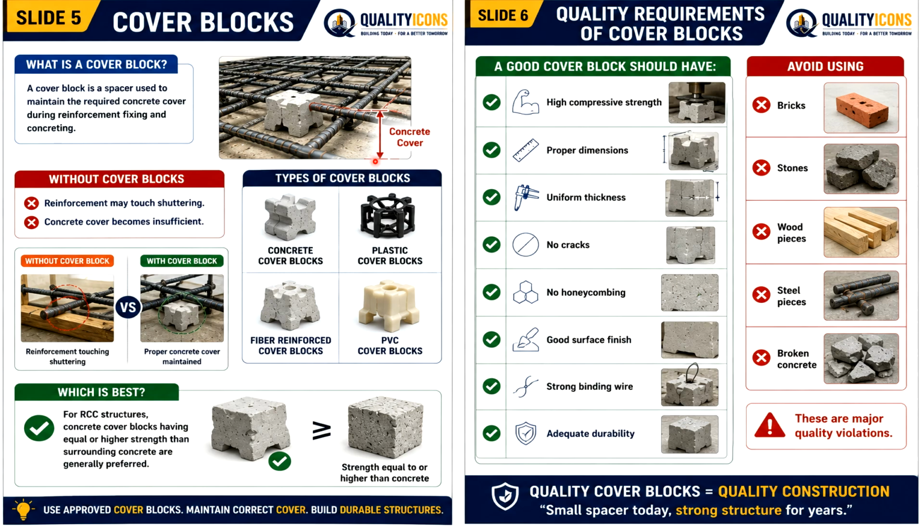During slab reinforcement inspection, you often see workers standing on reinforcement. This is a general mistake. Some cover blocks break, some move from their original position. So the locations are changing from one fixing point to another point.